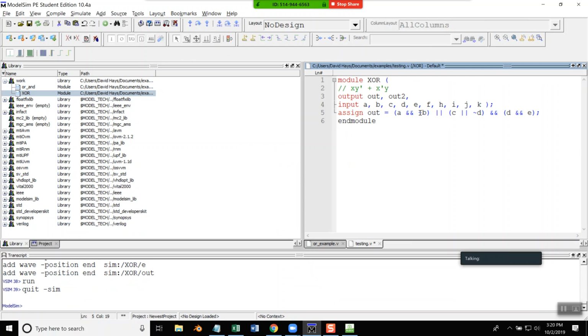If you look at the schematic for this, we only got 3 inputs. And so D is not actually an input, so you can't say it's an input. These are the only ones, because the inputs are the ones you actually will force voltage, whether it's 1 or 0. A and B are coming into this OR right here, and then it's going to give us a result that we need to send into here. So that's why you need something called a wire, as like an intermediate variable type of deal. Does that make sense on what the difference is between a wire and an input?